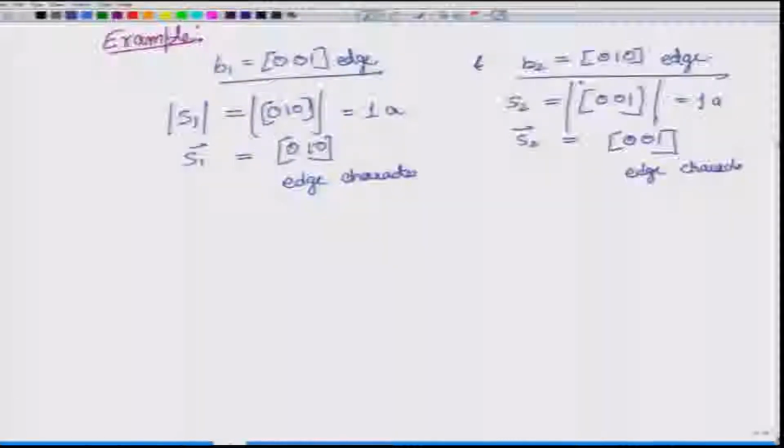So, for this particular information, all we needed was the Burgers vector, and we do not need to know whether it is an edge dislocation or a screw dislocation. So, this could as well be edge or screw.